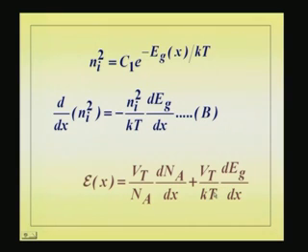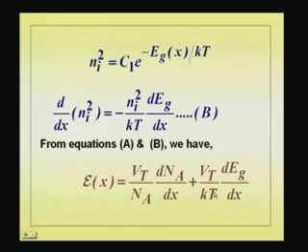Okay. Now, let us take a look at that. Okay, that was missing there. So, this is the formula that we have got now, which tells us what the electric field is at thermal equilibrium. Now, when you forward bias the emitter base junction and inject carriers, electrons, that electron experiences this built-in field. Okay. And what is the direction of this field?